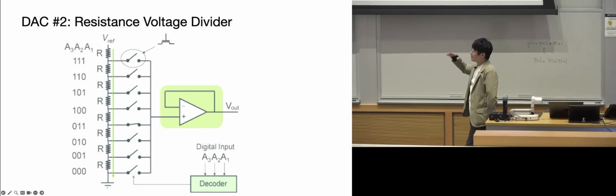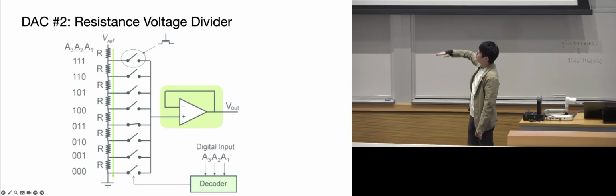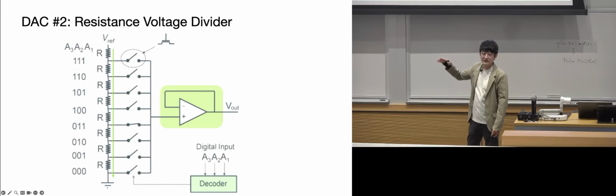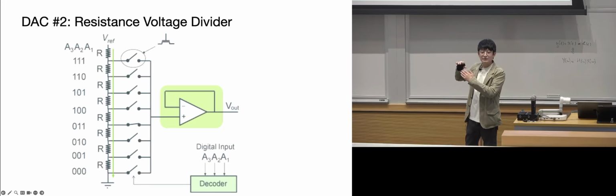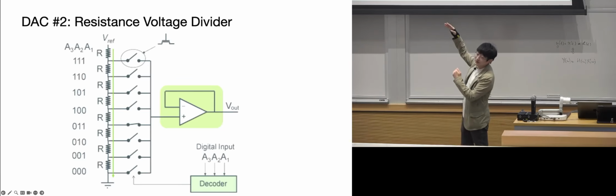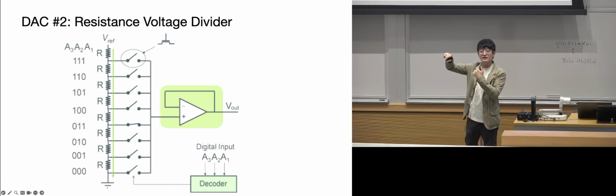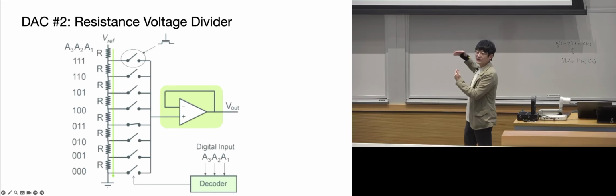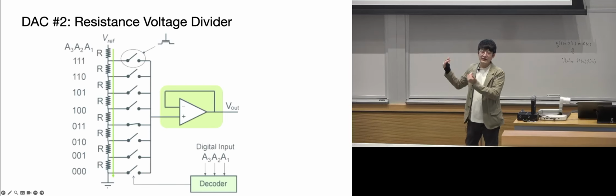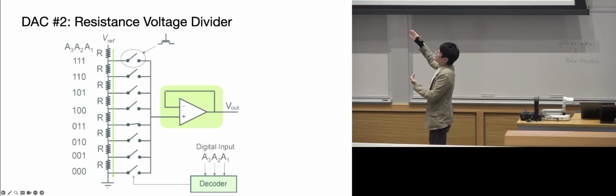On that one, you have the same value of voltage dividing each of the steps between 0 and the reference, and then you essentially compare the input voltage to whatever values this voltage divider can generate, and then decide on an ADC input value, right? A similar idea can be just adapted to the DAC as well.